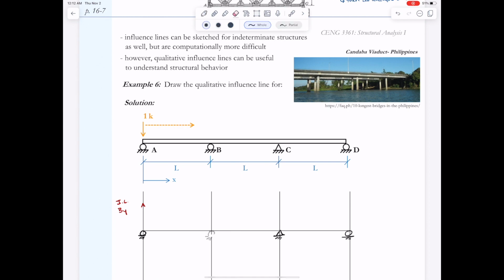And then I'm going to remove the reaction at point B, and I'm going to shift it up 1. But now you have to imagine I'm just shifting this up 1, but now the whole thing is bending to accommodate this. So what is my displaced shape under that bending? If I just move this up 1, but it's locked in at 0 at all the other supports, at points A, C, and D. So now when it's bending, it'll look something like this.